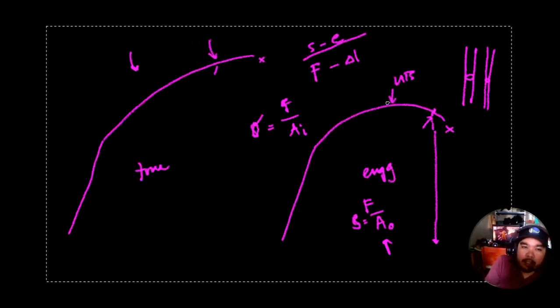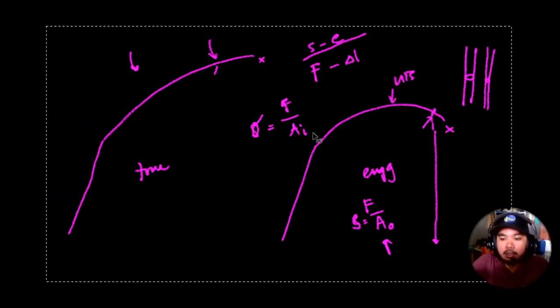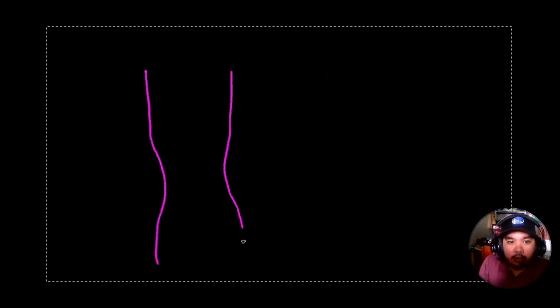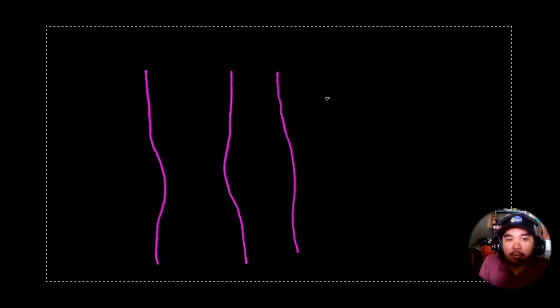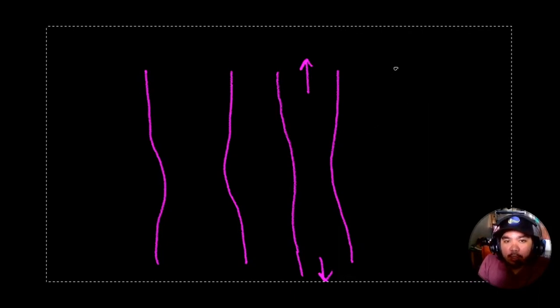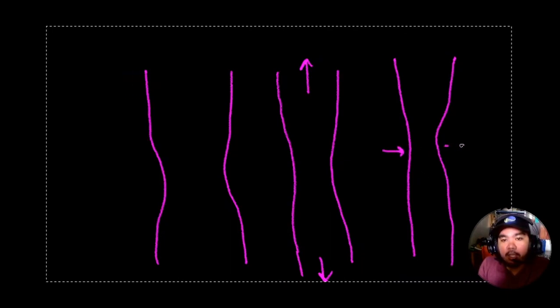Pero in general, past the UTS kasi kaya siya problematic because let me just draw, no? When we do the tensile stress or the compressive stresses, magkakaroon tayo ng ganito, something like this. So if we increase the amount of stress, mag-thin out yung metal natin. So ito yung dog bone natin, mag-thin out siya pero mag-expand siya ng ganyan. Tapos aabot siya sa point kung saan nagkakaroon ka ng necking, no? So necking is related to the point where we have your UTS.